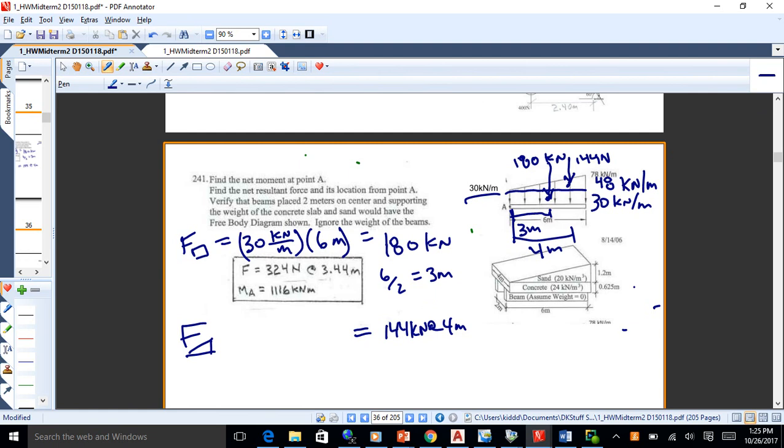For a triangle, how do you find the what's that called, the centroid? Yeah, it's 2/3 of the distance from the vertex. The centroid's located 1/3 of the distance over from the right angle and 2/3 of the distance over from the vertex. So the centroid's right there. That's d over 3, or whatever you want to call the variable, and that's 2d over 3, always. So you just find the moment caused by those two forces, and then find the force, divide them out, you get the distance.